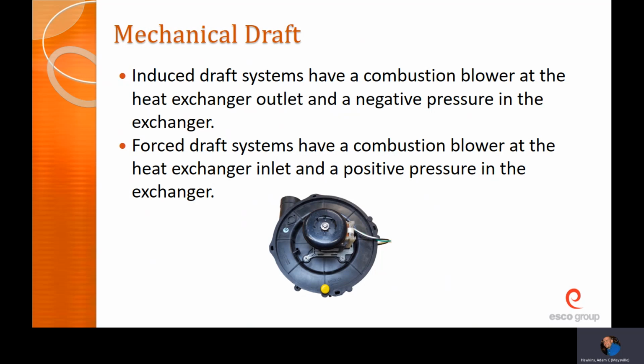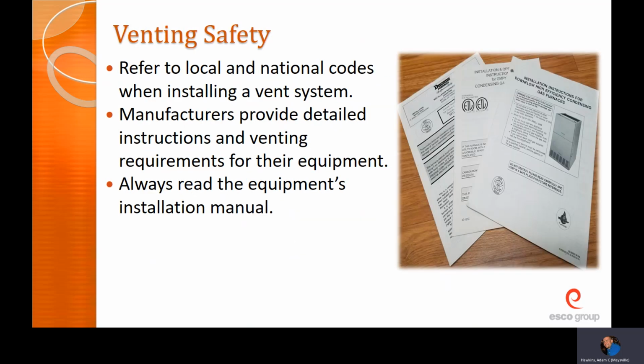That negative draft on your exchanger is going to pull that air in, versus a forced system that's positively pressurized, which is going to push that possible CO out into the house. So there's a little bit more of a safety factor with the negative pressure because it's less likely to make it into your house. That's the way I've always looked at it anyway. You don't see a lot of forced draft, or at least not in residential. In commercial boilers you may see some forced draft boilers, but you don't see a lot of them in furnaces.